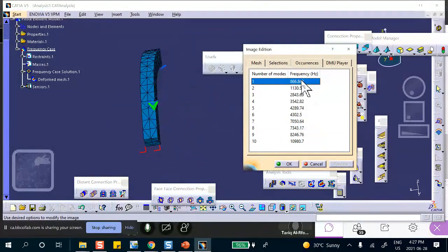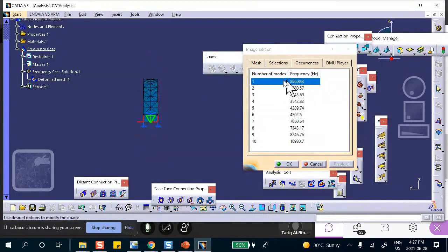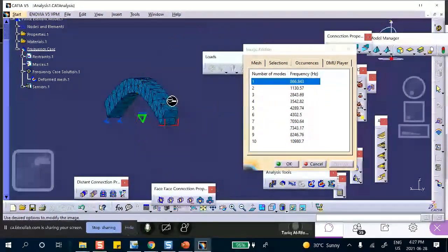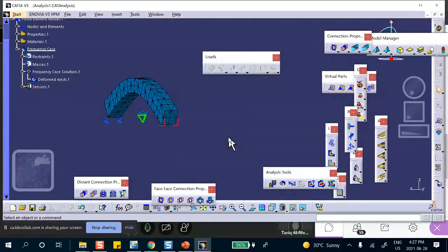This is the most critical one. If the fan hits that RPM, converted to hertz, this guy starts wildly oscillating. If there is no damping, eventually the amplitude goes to infinity and it fails. The reason in real life it doesn't fail like that is there is damping. This is an undamped free vibration. Okay. Are there any questions at this point?